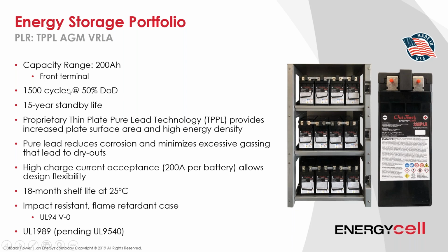In fact, the other thing too, I'd say is if your customer just wants to do net metering and just have emergency backup power, I definitely recommend the PLR battery for that, because it does have a long standby life, low self-discharge. And at 80% depth of discharge, this drops down to 675. But if you're only going to discharge your batteries a few days, a few weeks out of the year, it doesn't matter.